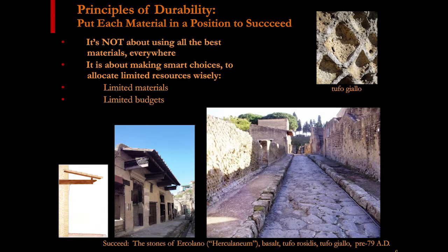So the way they made the stone more durable was big roof overhangs like you see here, and then a sacrificial coat of plaster on top of that. So keeping the water off it, and then if something's going to get wet and deteriorate, it's not your structural wall, it's just this kind of sacrificial plaster parge coat.